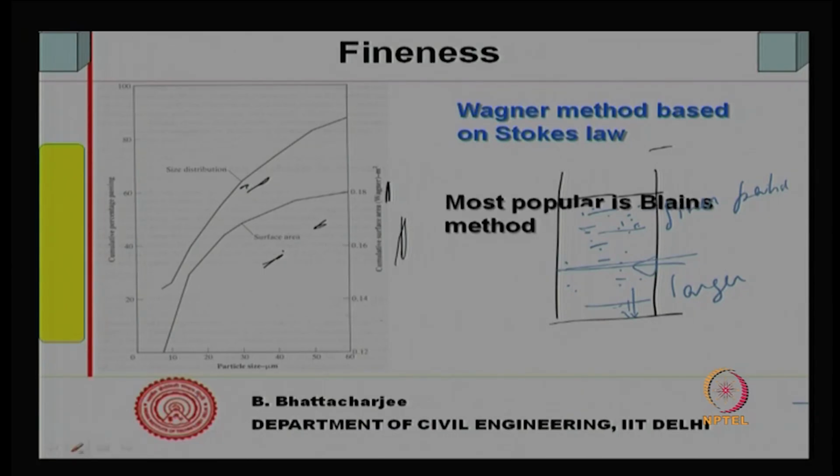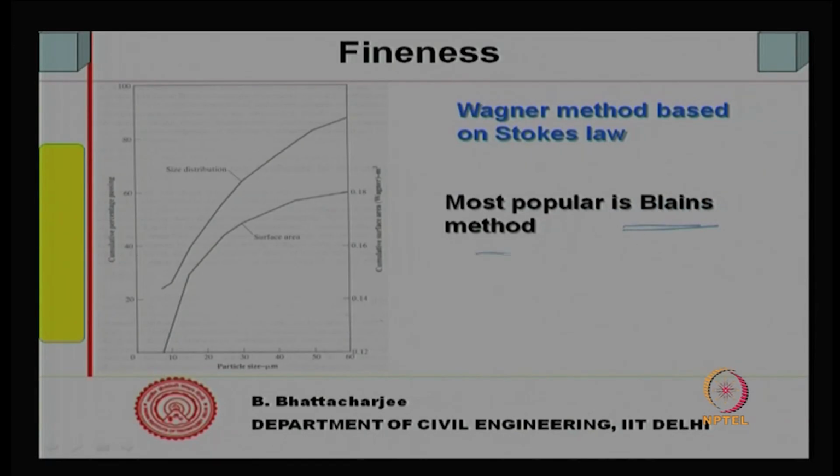Right. Now, most popular of course is Blaine's surface area measurement. You see, there are other surface area measurements, and the most popular is Blaine's method for measurement of surface area. So, let us see what